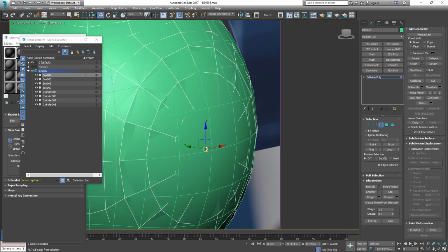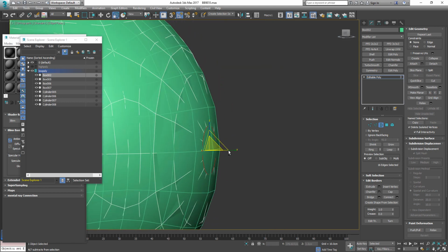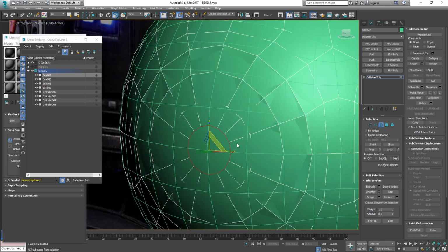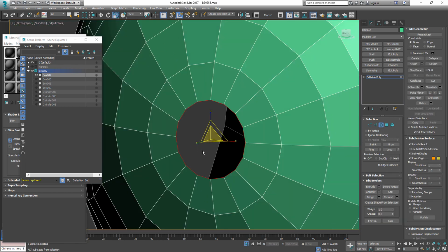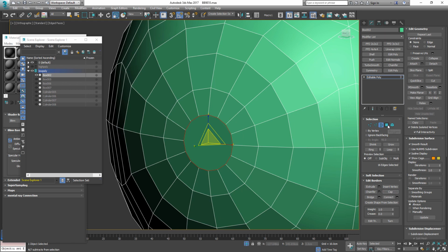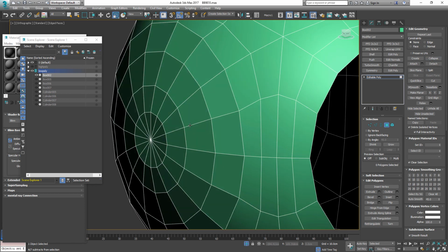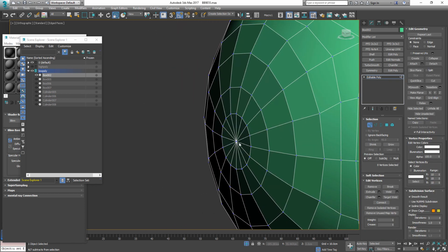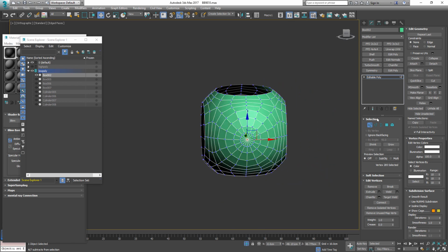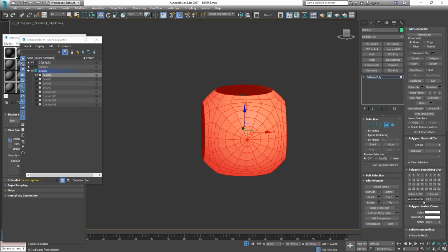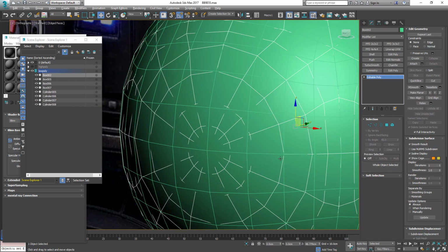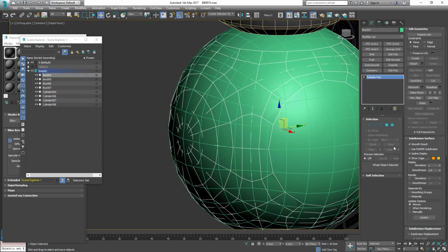I'm gonna add another edge loop here and another. Gonna scale that one down a little bit. So we have 3 extra edge loops created. And now I'm just gonna cap it and take that one here and give it one more inset that I'm gonna collapse. So now let's select that vertex here and push it out a slight bit so that we have a nice curvature. And then I'm just gonna auto smooth everything here. So we have 1 smoothing group.